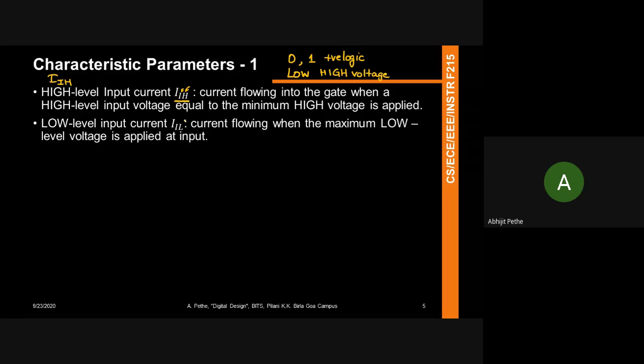So what this means is when you're going to design the circuit, you need to also ensure that you're flowing this much current, right? As a circuit designer, when you're designing your board, it is not enough that you just apply a voltage. The voltage source that you've applied at this pin should also be able to source this much current. If the voltage source is not able to give you this current, then the IC is going to malfunction, because it's not able to hit your IIH or IIL requirement, right?